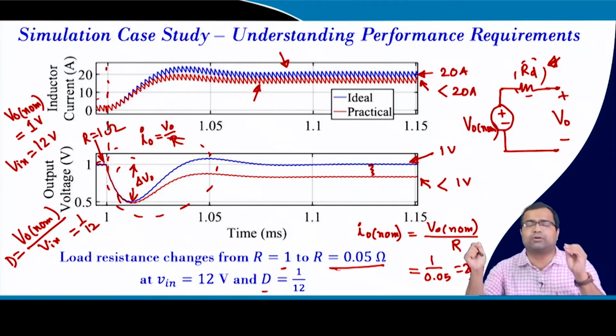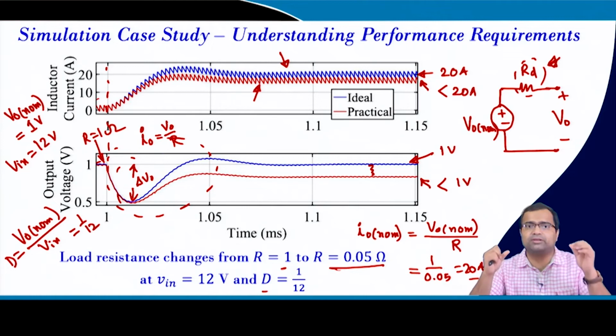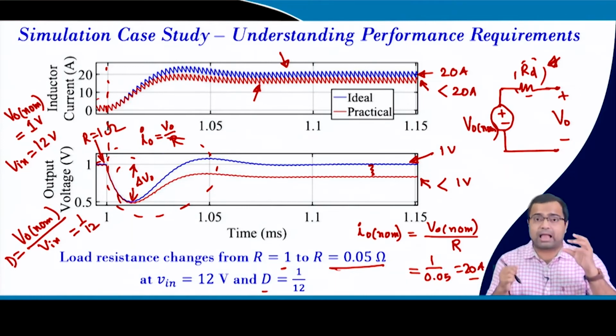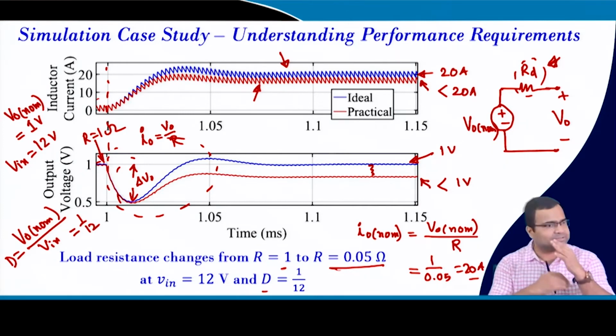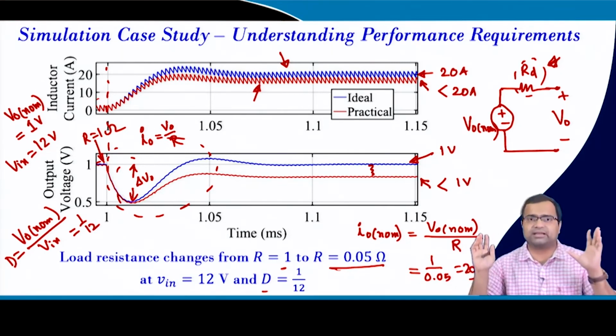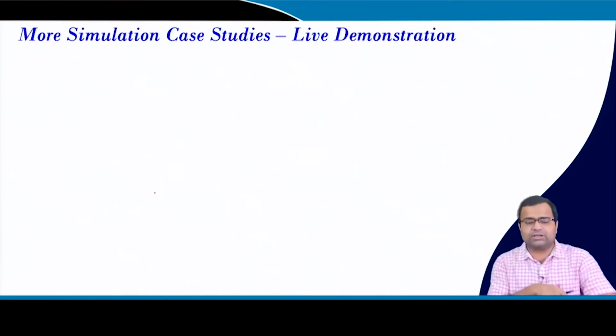So the DC-DC converter has to be tightly regulated within the noise margin of the digital circuit. We need to apply some control logic such that the undershoot can be substantially reduced, so that the whole voltage profile is within the limit of the digital circuit for which we are designing the power supply. That motivates us that we need closed loop control.